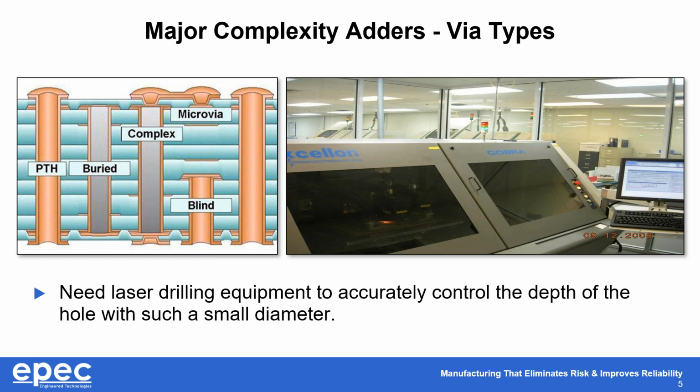Do you have to outsource laser drilling, which a lot of companies do? Well, it's really hard to do a 3-day turn when you're having to outsource the micro via drilling, and you're going to lose 2 days, 1 day shipping there, 1 day shipping back. Right, so that's kind of why these things matter. Now, if you just had plated through holes, it doesn't have to go anywhere. But if you have buried micro vias, that's really a different animal, and it's really understanding how that's going to affect your lead time issues.